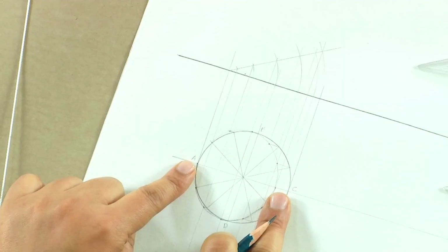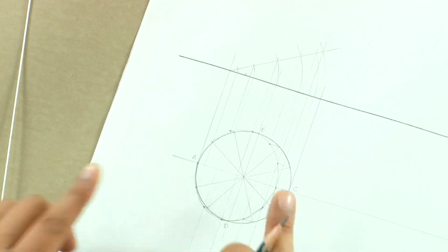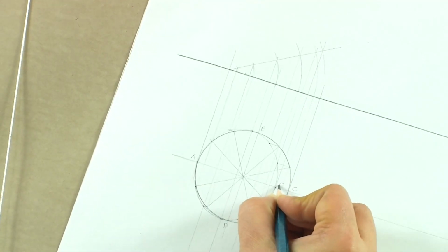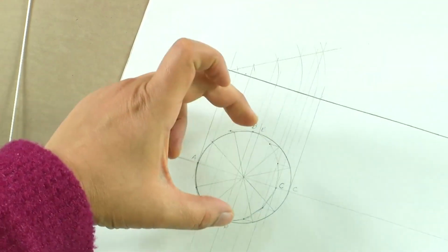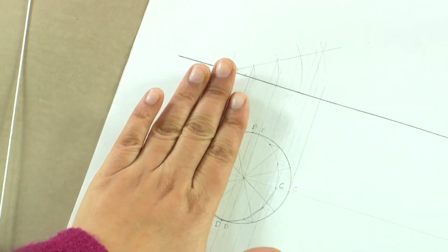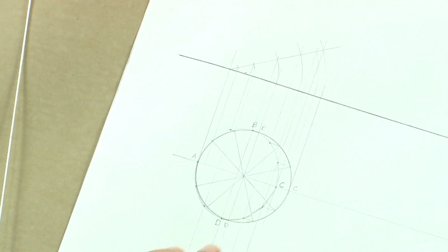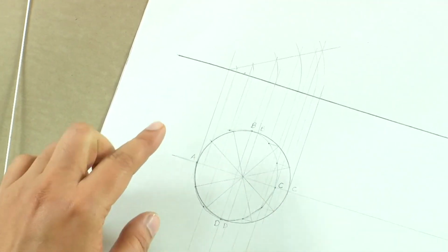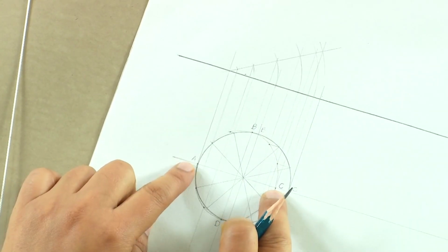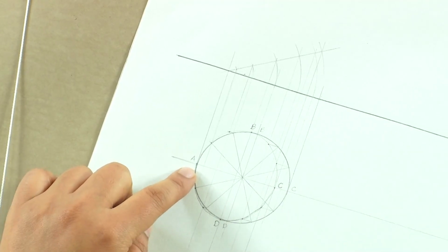Alright, so this is the ellipse that we get when this circle is inclined at 30 degrees to the HP, and here what we are seeing is that this point C has shifted. So, we now have this point C, B and D. Now, BD is still intact because it is still parallel to this HP. Now, what we have to do next is we have to incline this ellipse in such a manner that AC now makes an angle of 30 degrees with VP also.